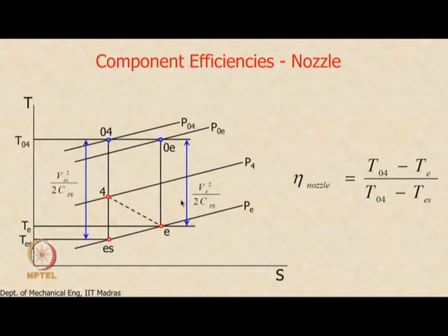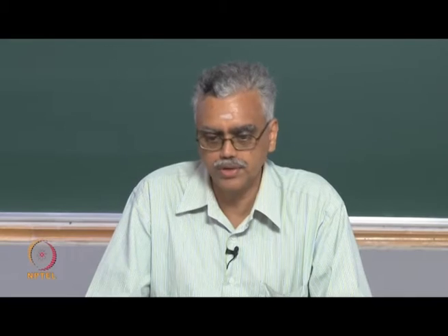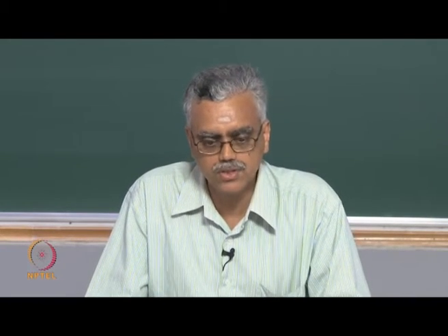So, how do we evaluate the critical pressure for a nozzle in which there are irreversibilities? So, previously the nozzle process was isentropic, now it is irreversible. So, we need to make sure that we know how to do that. How do we evaluate this PE? Right? That is the extra complication with the nozzle. Let us see how we do that. So, we take this situation one at a time. The nozzle is not choked, that is a simple case.